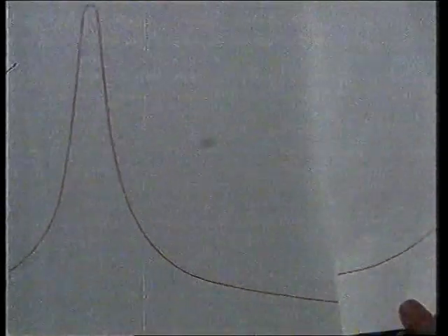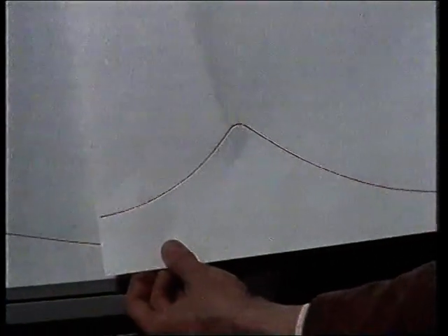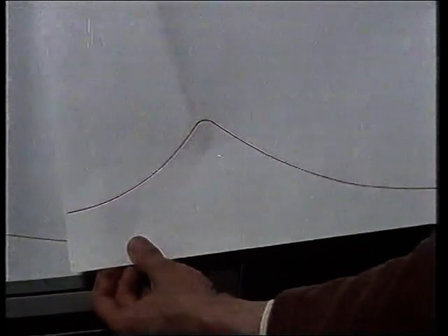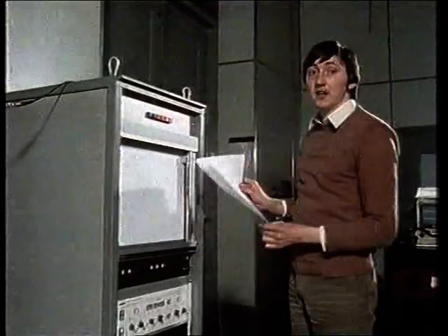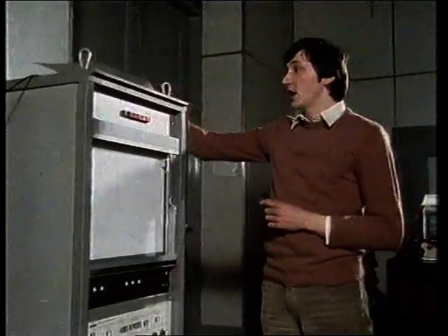That sharp peak has been greatly smoothed out. Less amplitude of vibration, less stress on the honeycomb, and the new design has got a life which is over 5 times the original. So that's not a bad return for the investment of a little bit of vibration theory.